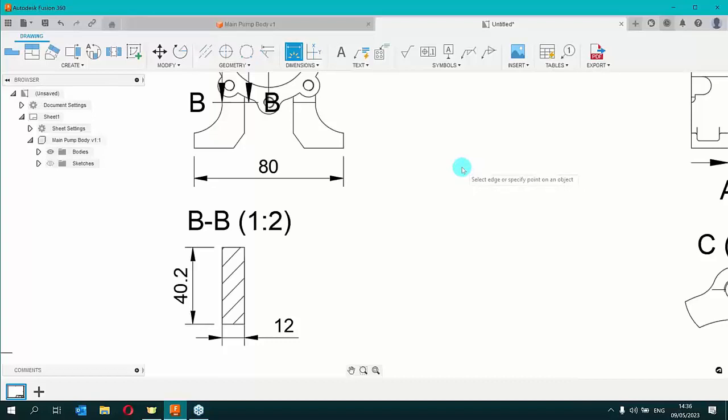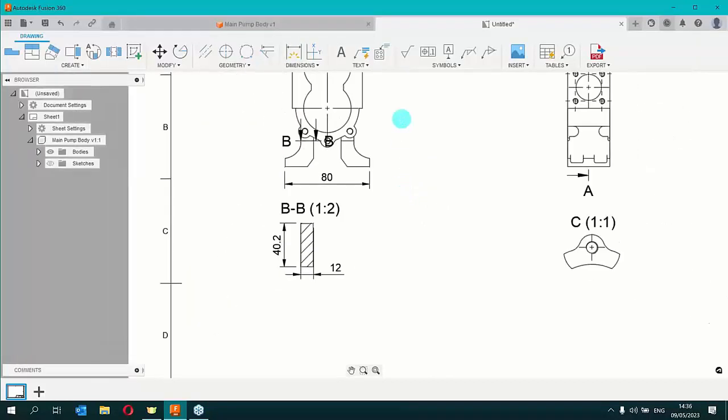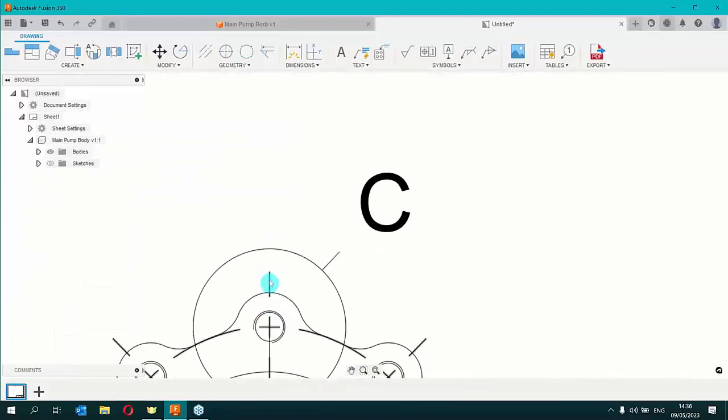Now in this case, once we've placed this in position, I have the ability to also add in any other changes that I want to make. So if I hit OK here and I want to reactivate the little tolerance or dimension there, I can hit the letter D for dimension on my keyboard here. I can pick the starting or the end point of that line.